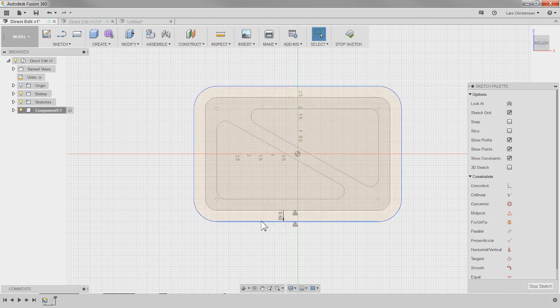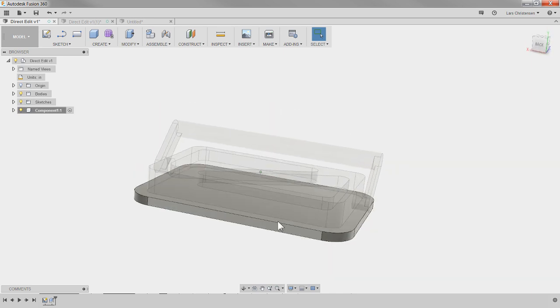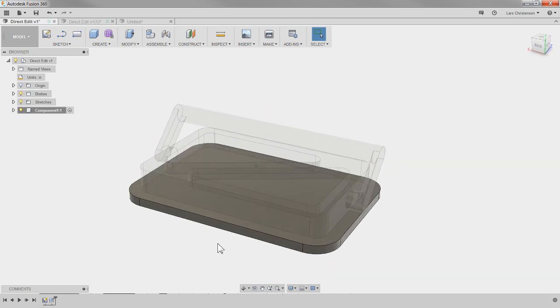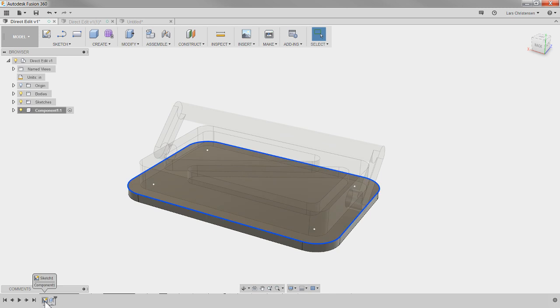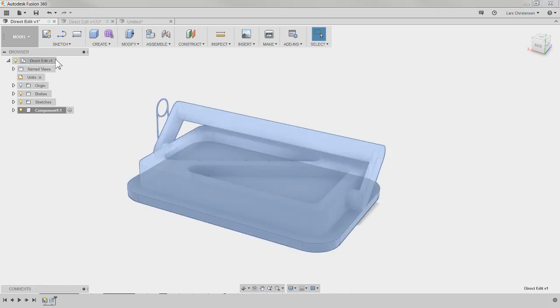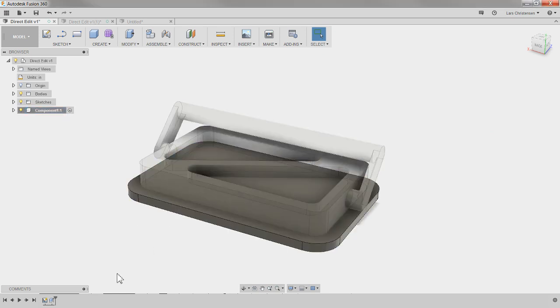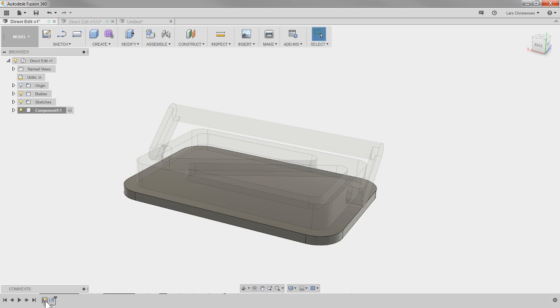So that means right now, if I need to make any changes to that second component, to this bottom piece, if we're doing standard modeling, I'm tied in with how that sketch was offset. I really hope this makes sense. The sketch we just looked at that forms this bottom piece was offset from this boundary right here. So if I had to make a change to this component, it could be kind of hard, right? I'm limited to the sketch.